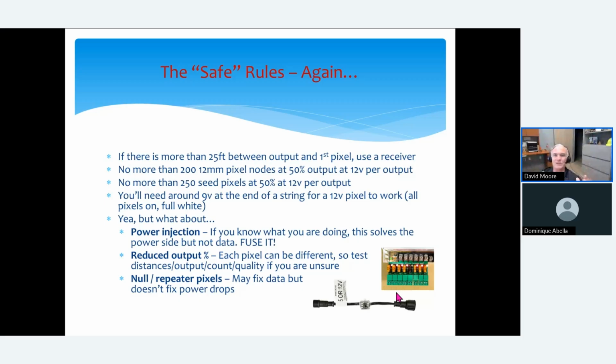But that doesn't mean that you can pump 9 inches of pipe of water through your faucet, because that power supply might be capable of delivering lots of power, 600 watts, but by the time it gets to the end of the pixel at the very end, because that's what matters, is how much power can you get down the wire, that's not what's going to be there. It's the same thing, again, if you use water hoses. Anybody's ever put a 100-foot water hose on another 100-foot water hose, and then another 100-foot? The water barely comes out at the end. But the pressure at the very front of the faucet is exactly the same. It's the losses in the wire.